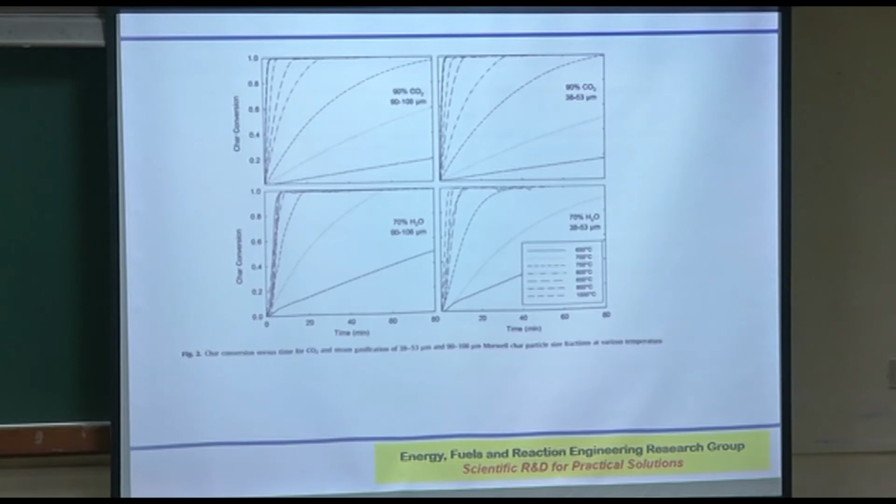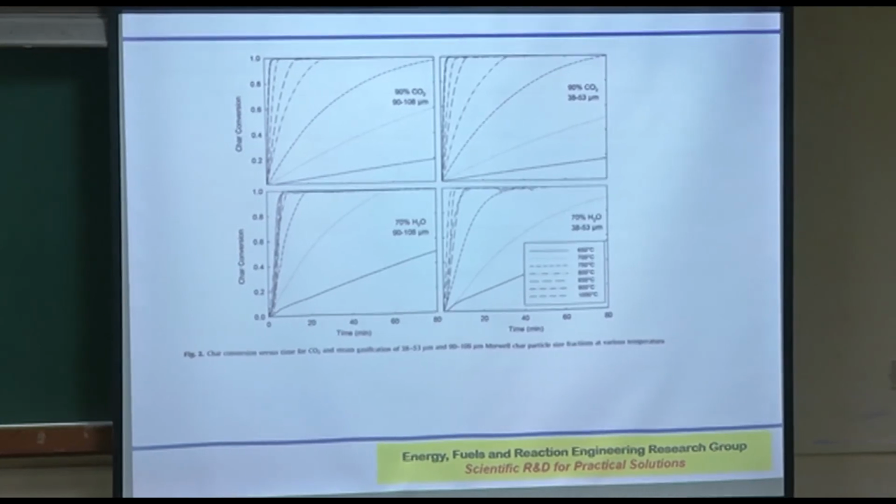Correct. Because the TGA is constantly measuring the weight. So when it has reached your temperature, let's pick one experiment, say 850. It will release some amount of volatile, and how much it is releasing, you can see it from the TGA. Absolutely precisely.